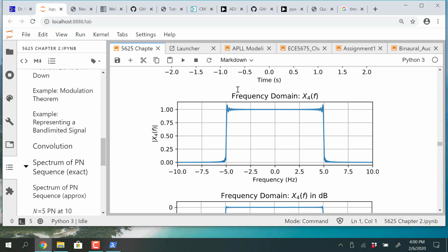The only problem is that because I've truncated the sinc function, I have the same problem that exists for Fourier series, namely that if you're trying to synthesize a Fourier series from its coefficients, you always get ringing on the edges of the square wave or pulse train. It's called the Gibbs phenomenon, and it's because, although you can synthesize any periodic signal, one shortcoming of the Fourier series is that it does not converge pointwise everywhere.